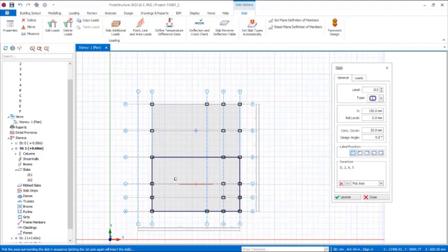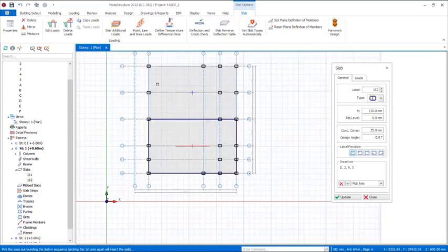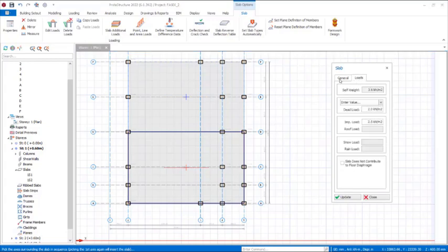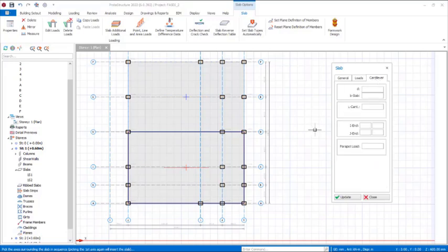Okay, now this time around we are going to be inserting another slab, so that we can have a very nice walkway around the structure. So for us to do that, we will click on these provisions. You right click right there. We are going to be using slab option 12, this one. So click on that, come to these provisions. It's going to be a kind of cantilever slab right there.